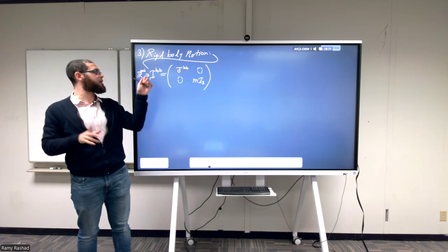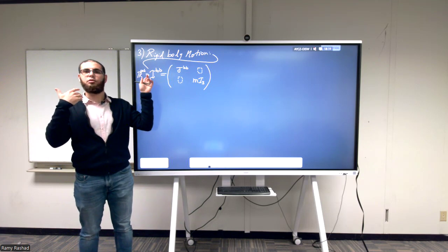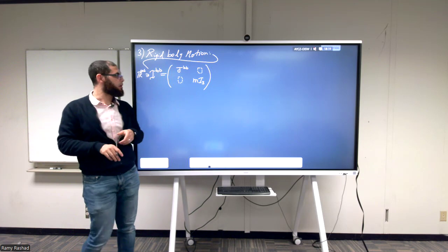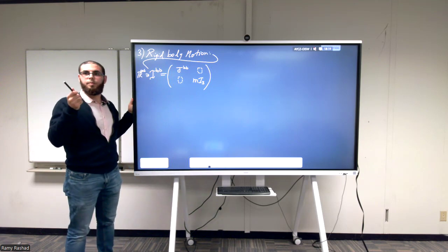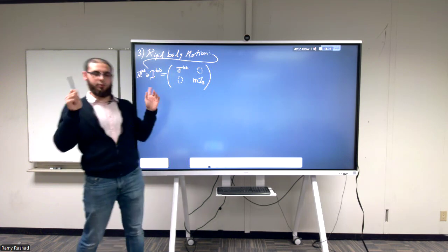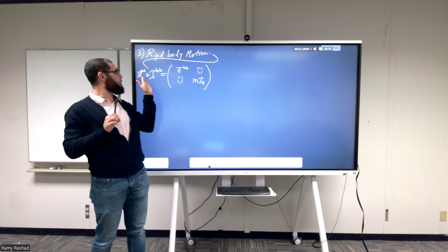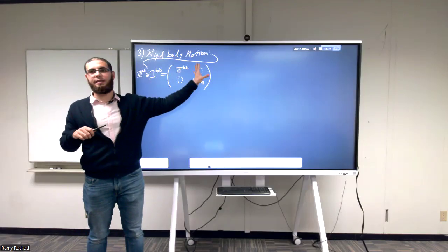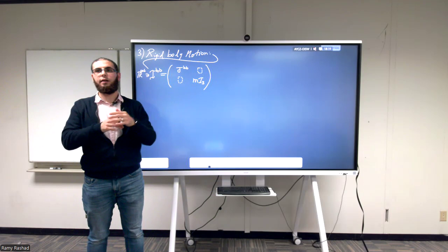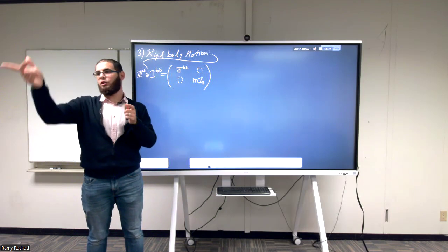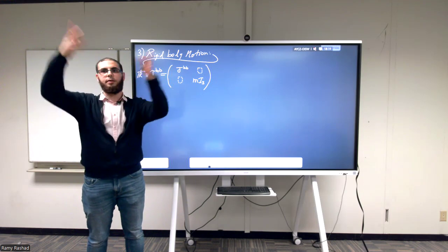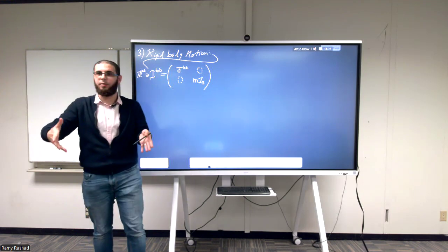Let's assume for simplicity that we're going to be putting B at the center of mass frame. First, the generalized inertia tensor is a symmetric 6x6 matrix. This is the most general thing that you have. You choose a frame B and put it on the object that you're talking about, the rigid body, the end effector of the robot, the frame that's moving with the robot body itself.